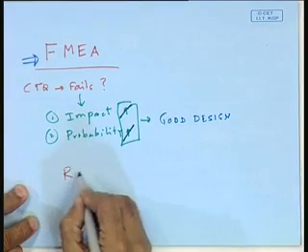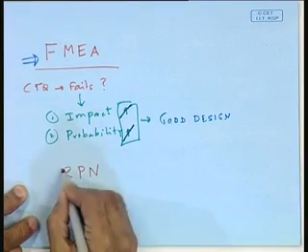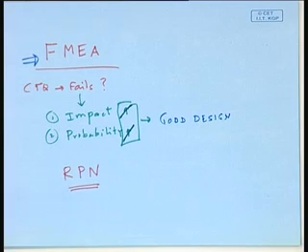Then you will also ask, when this product is used in the field, how likely is it to fail? So this is now the issue not of the impact, but the likelihood. The product of these two quantities, impact multiplied by the likelihood of failure, is the quantity that is called RPN, risk priority number. And the higher the RPN, the more dangerous that design is. The more likely that the use of the design is going to be dangerous.